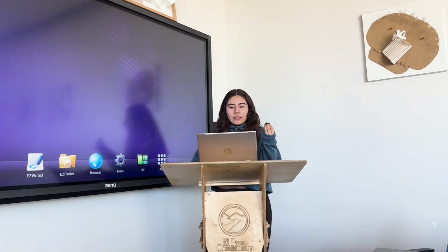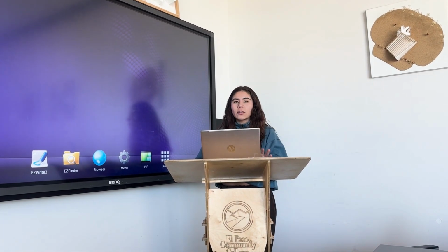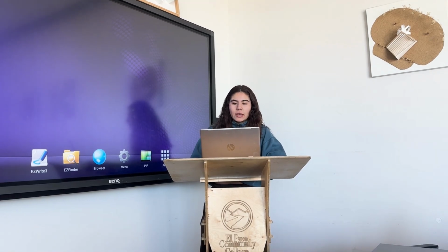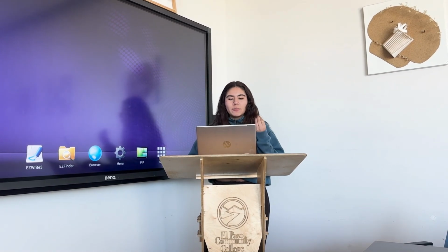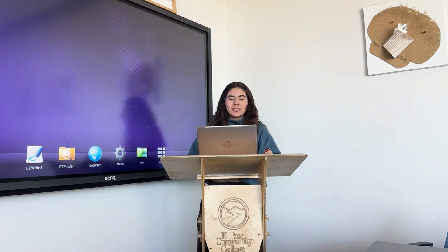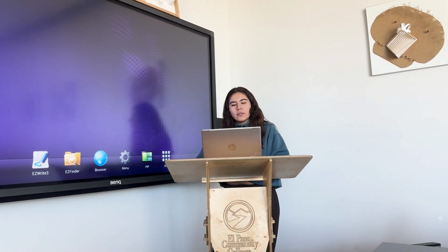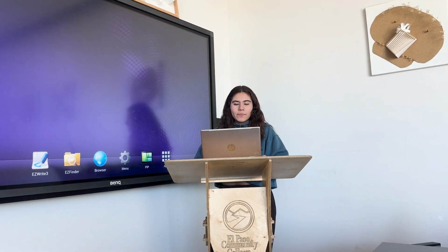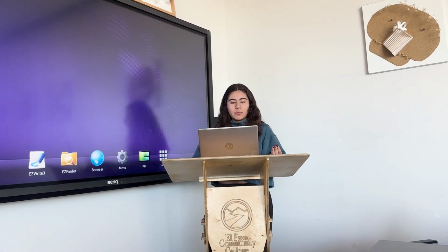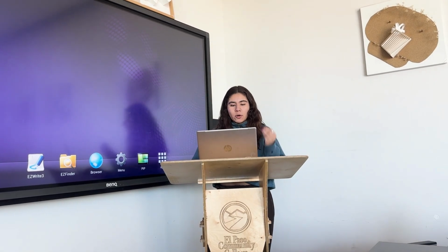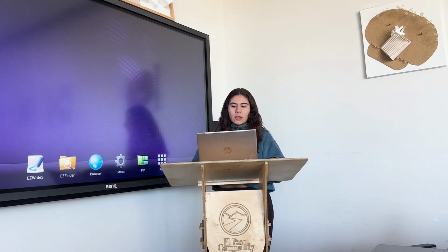New clay masonry units tend to absorb water and expand gradually under normal atmospheric conditions. New concrete masonry units usually shrink somewhat as they give up excess water following manufacture. Expansion and shrinkage in masonry materials are small compared to the moisture movement in wood or the thermal movement in plastics or aluminum. Still, these changes must be taken into consideration in the design of a building by providing joints of the appropriate types to prevent excessive forces that could crack or spoil the masonry.